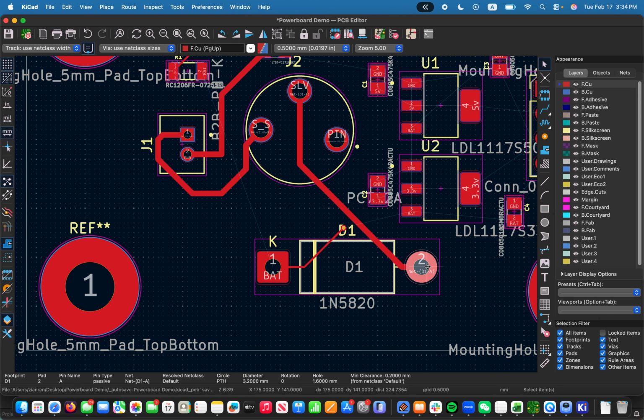On through-hole components, since the hole goes through the top layer and the bottom layer of your PCB, you can do the red layer or the blue layer for tracing, so the top layer or the bottom layer for tracing, and they will both accept it. So let me keep tracing from here.